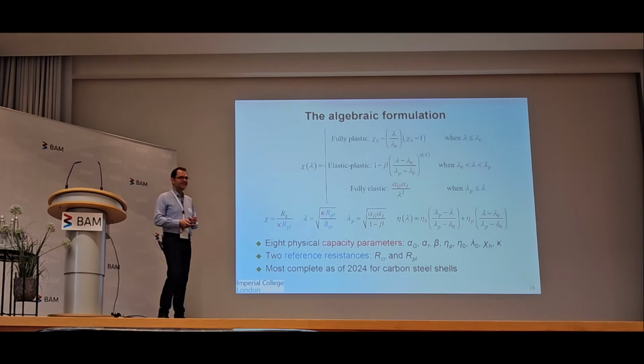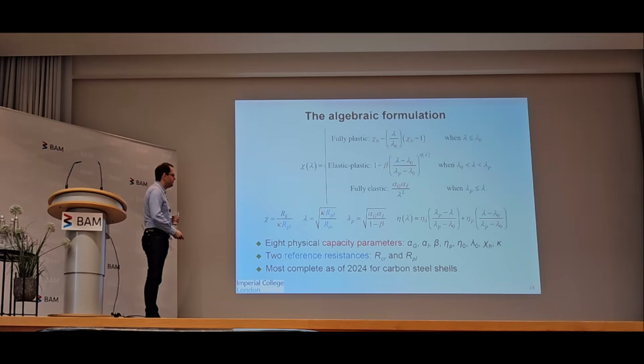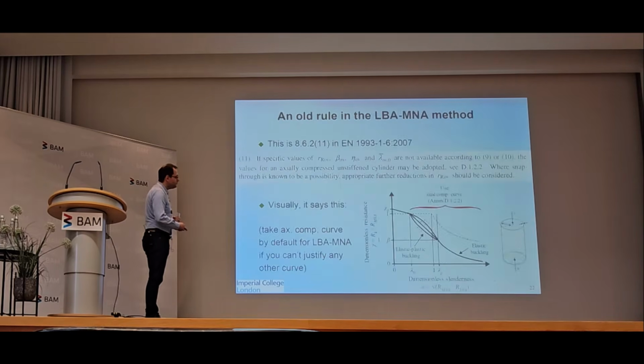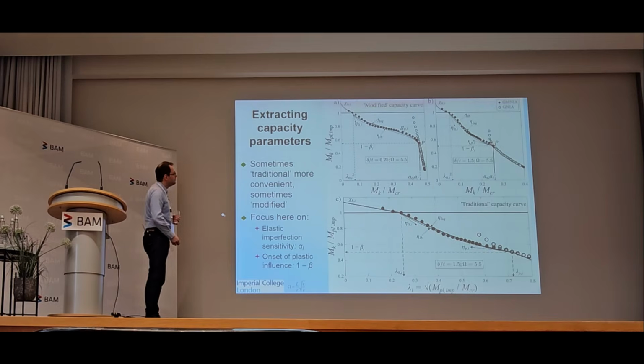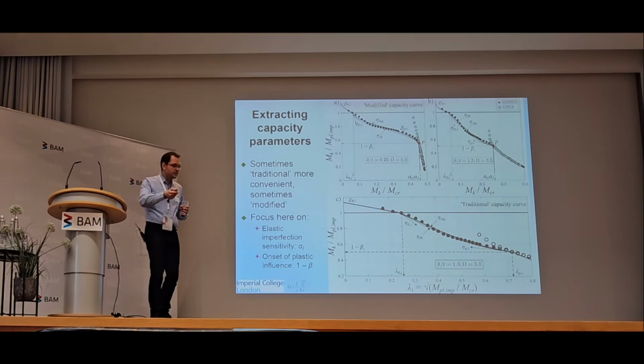I have a question regarding your slide number 25. It's on the beta, which indicates first yield or limit between elastic region and partial plastic. It indicates the point of this curve where plasticity has a noticeable effect. So I'm sure a little earlier there might be some localized surface yielding somewhere, but if it doesn't have a significant effect, this won't affect the resistance much.